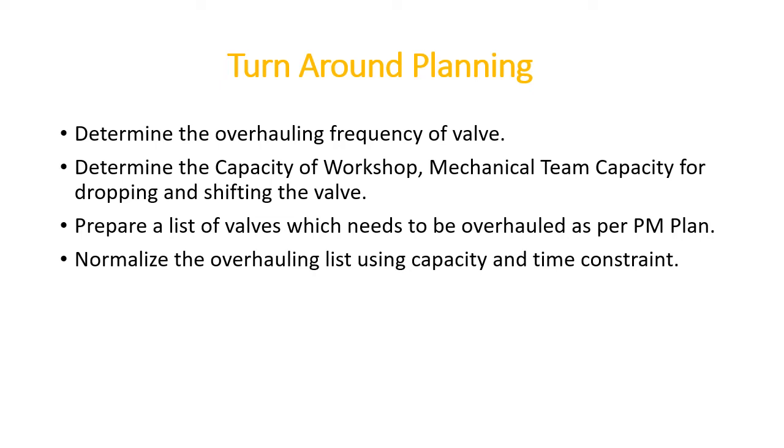Now the problem with overhauling all the valves in the turnaround or shutdown is that the shutdown window is very small. If you try to complete the overhauling of all the valves in the complex within that window, it will be a huge task, because the capacity of the workshop is limited, and the mechanical team is also limited.